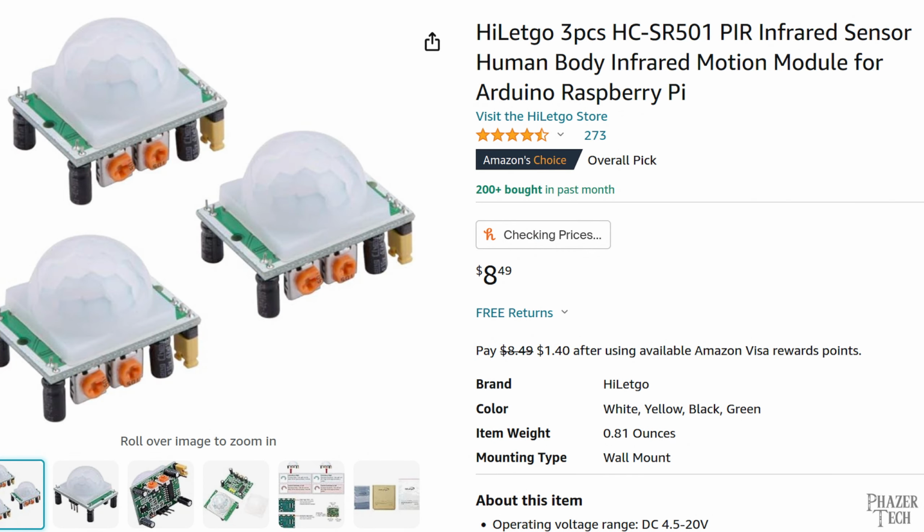But in other situations where there's no patio light and everything is pitch dark, then this approach would be pretty useless, in which case you'd likely want to use a PIR sensor instead, which can be purchased for only a few dollars if you wanted to integrate that with the Pi. But like I said earlier, these don't work through glass, and in my particular case, I want everything to be inside the house, so a PIR sensor wouldn't work for me here. But I might cover these in a future video that focuses on how to use the Raspberry Pi's input pins in Python.